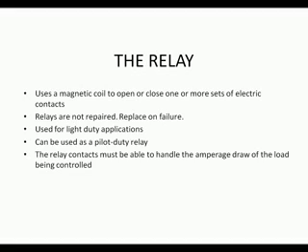There's different motor amperages to deal with. First of all, running load amp, RLA, is similar to full load amperage. It is the amperage drawn by the motor while operating. Locked rotor amperage, LRA, is the amperage drawn by the motor at startup, 5 to 7 times greater than the RLA. Both LRA and RLA must be considered when choosing a control device.